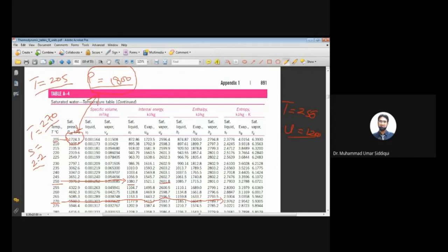Is this point clear? Yes, sir. So, sir, what will happen in superheated? Suppose the pressure was 1600. When you compare pressure with pressure, 1600 is less than 1724.3, so that means it will not be compressed liquid, it will be superheated. This is only for the pressure case.